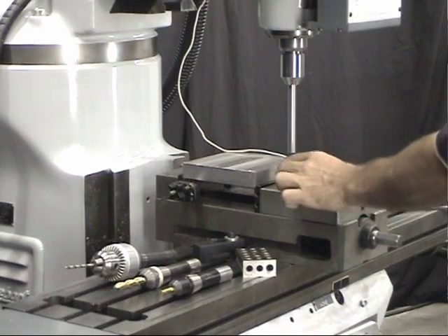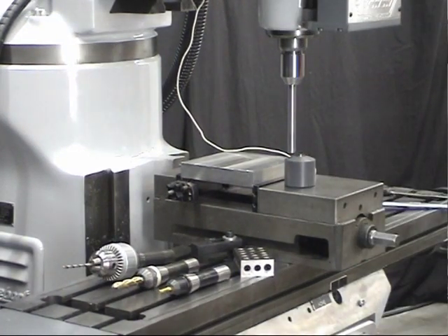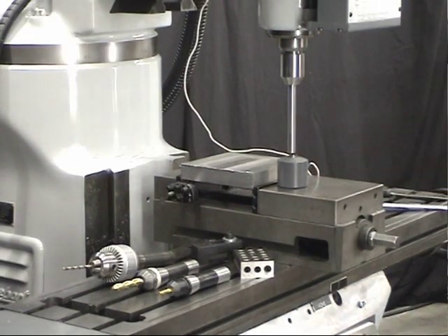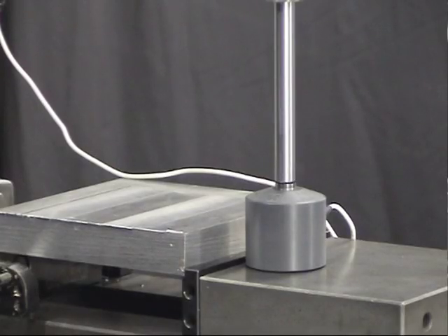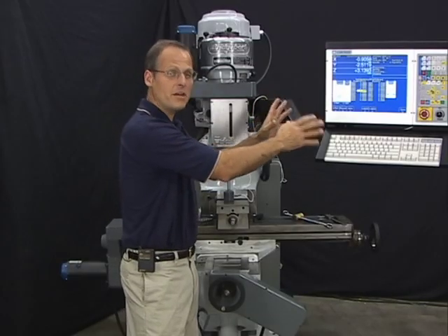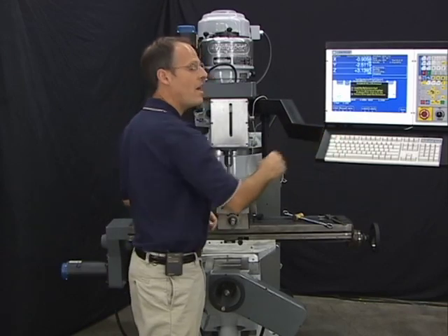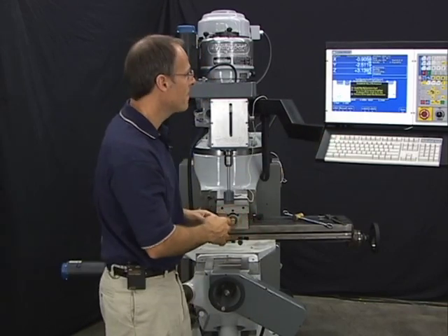And again, I want to reduce the distance between the reference tool and the TT1, just like I did on the 1, 2, 3 block, so that it's only like 10, 20 thousandths or so, but not touching. When using the TT1, you still have to set a reference position. So using the same tool height offset menu that I was in before, I'm actually going to hit the exact same F1 ZREF button as I did before with the 1, 2, 3 block.